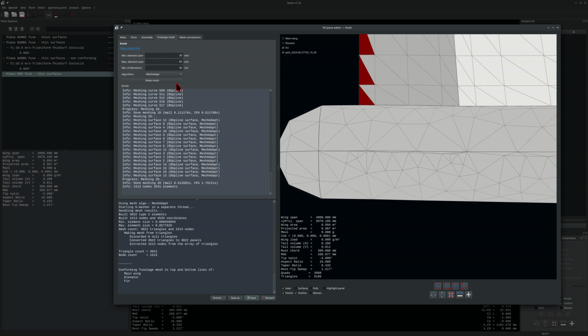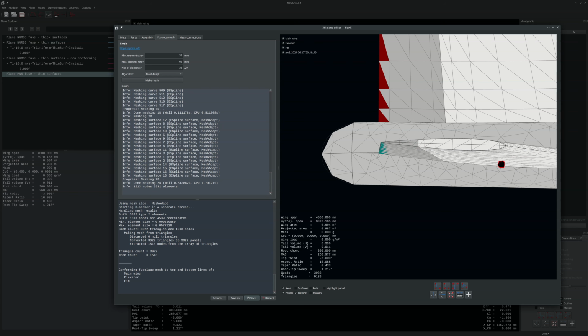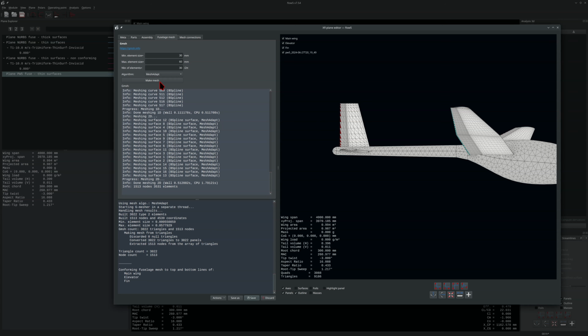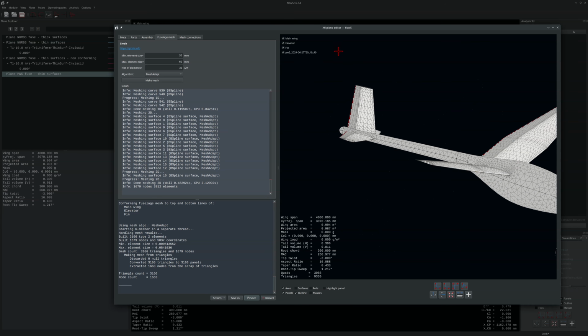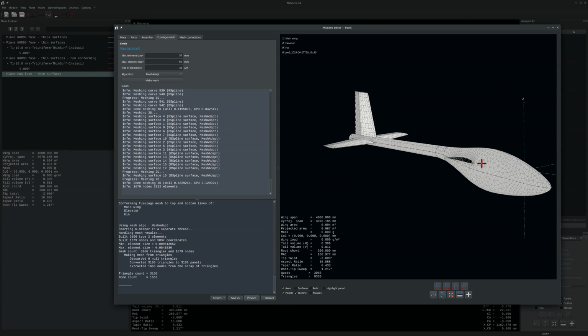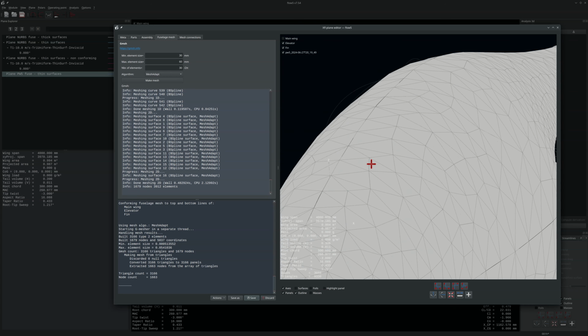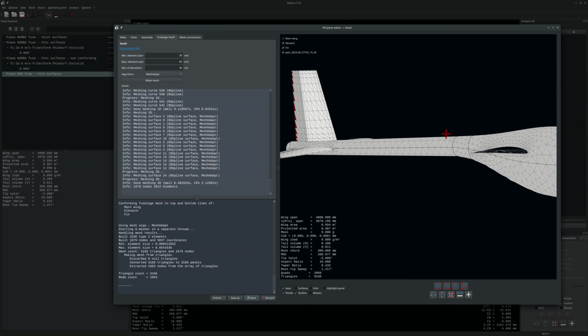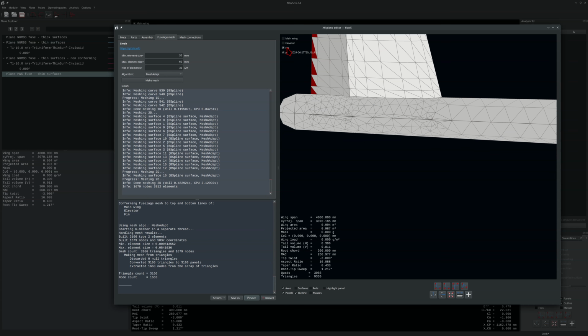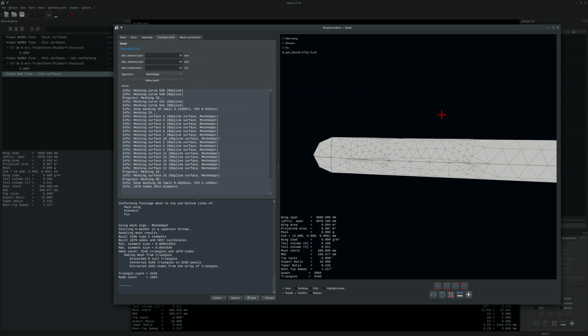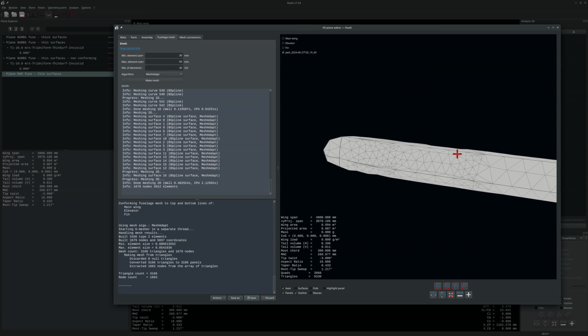Well, let's try it. Show the elevator and the main wing and run with the mesh and see what happens. Let's hide the wing, main wing. So things went well at the front. We have our conforming mesh, which is good. Let's see what went on at the tail. I think it didn't go so well. Yep. And in this case, I'm not sure why. Let's center the view on the tail. Neither the fin nor the elevator were cut clean open.